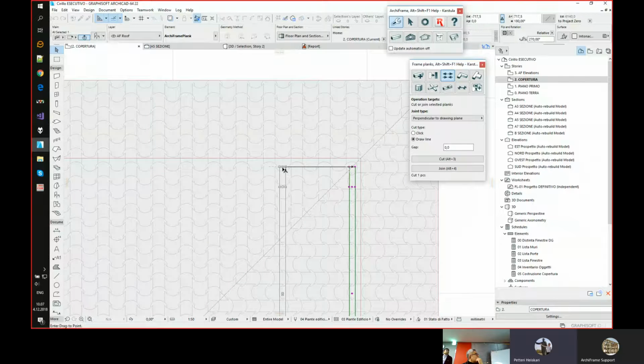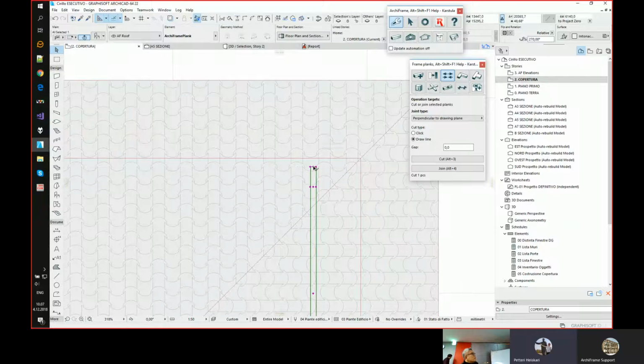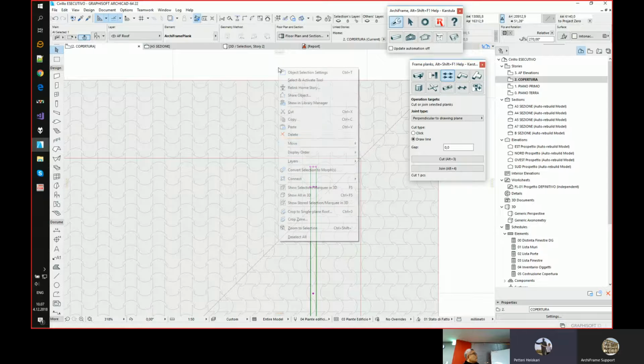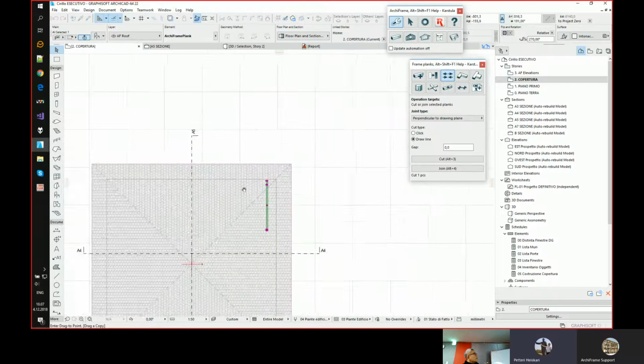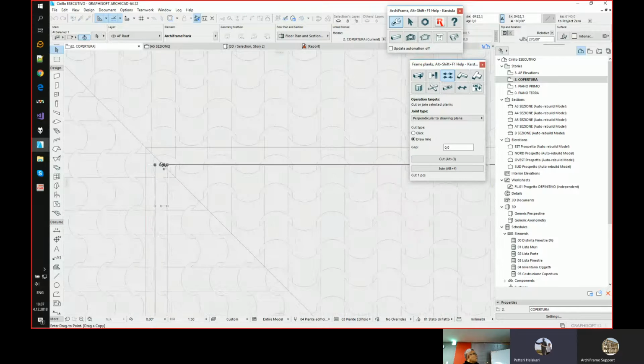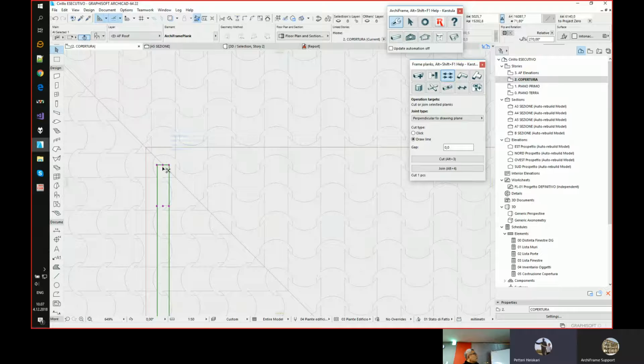So just normal ArchiCAD tools, drag this piece from here, and I'll place it exactly here at the roof line, and then I reposition it slightly. Starting from here, and from the keyboard I press R like radius and enter value of 400 millimeters. Then I drag a copy to the other side, starting from the middle point and placing it here, and then again, now I do this from keyboard, Command D, to drag and radius of 400 millimeters.